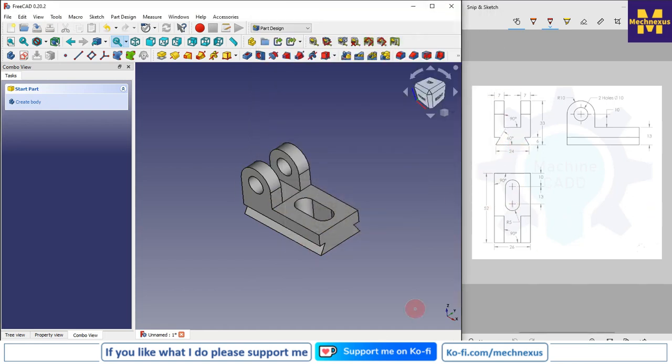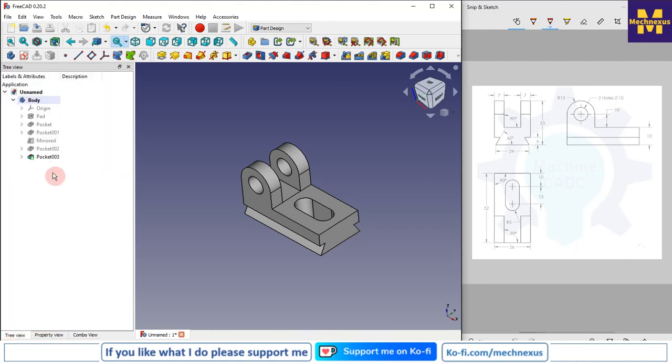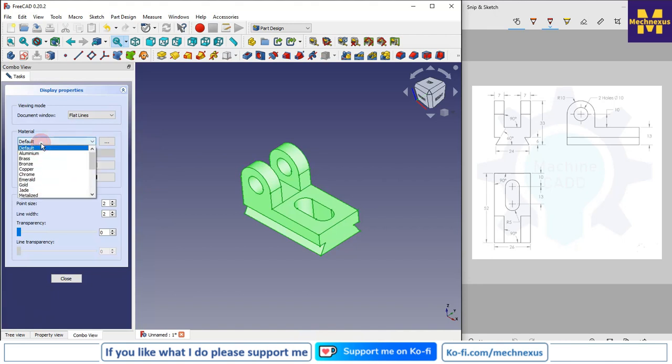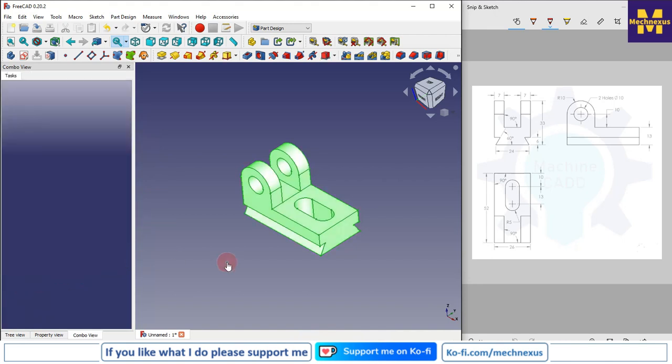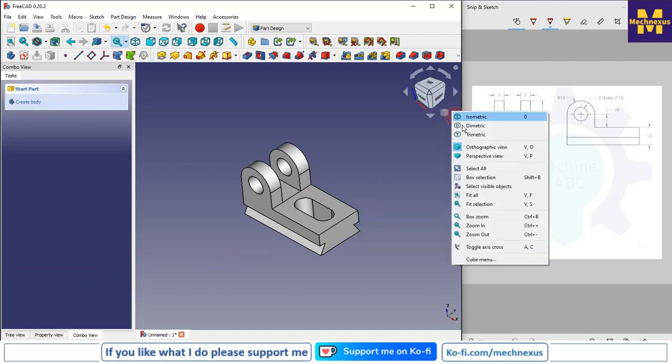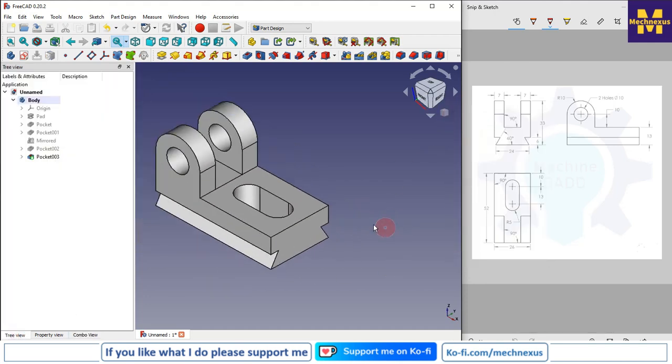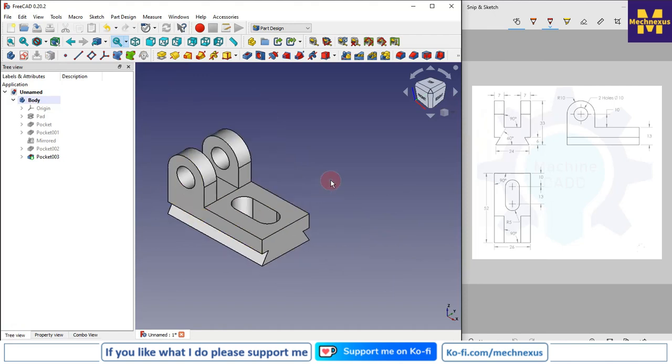Now we will give some random color or some material to our part. So I will go simply to the appearances, and I prefer to give the chrome, and I will close it, and I will set it to the isometric view. So this is how we have successfully converted this part into the 3D solid.